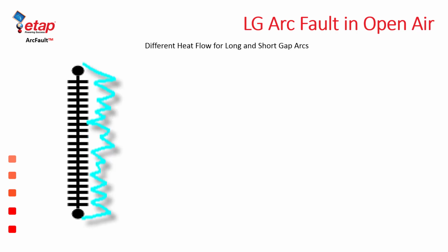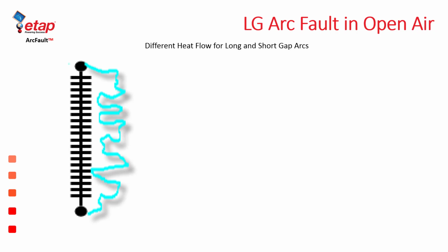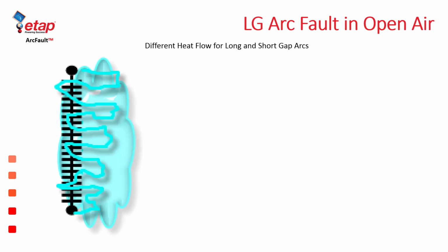As the arc proceeds further in time, it elongates and expands, and it continues doing so as more cycles go forward. Eventually, as the air around the arc ionizes and starts to convert molecules into ionized particles, we have this plasma cloud that forms around it.